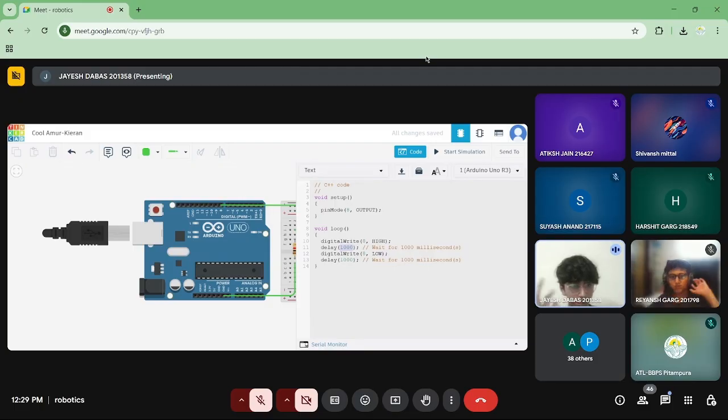So we have used 1000 here. अब would this stop for 1000 seconds? No. Why? Because originally in the coding language, in this language for Arduino, delay में हम जो भी value कहते हैं, it is taken as milliseconds unless we tell it कि ये seconds है. तो अगर मैं delay में 5000 लिख देता हूँ, तो that implies 5000 milliseconds, which is essentially 5 seconds. तो 5 seconds के लिए रुकेगा.